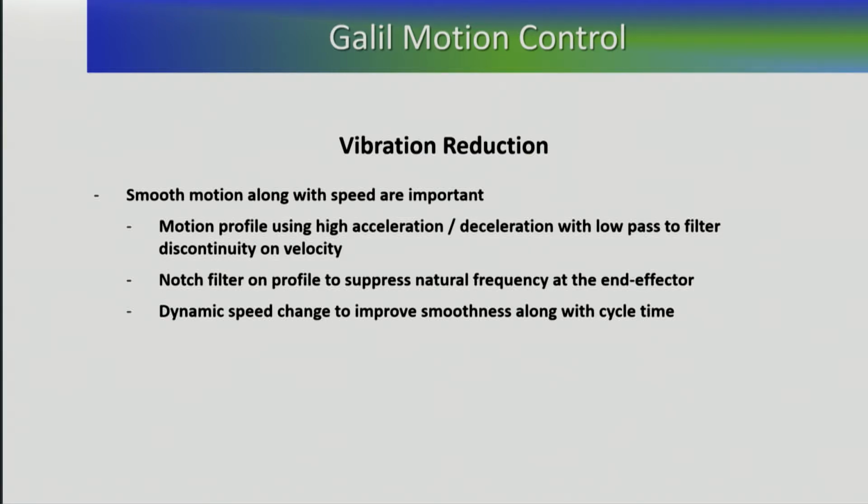When you're trying to address that, you basically have to say, I'm going to take the profile, and taking the profile, put it through the filter so that I can apply either a low pass and eliminate certain frequencies, or apply a notch on my profile. That allows me to eliminate a specific frequency or band of frequencies that do not go into the plant. And as a result, you no longer are going to be able to excite the resonance. So you do have an option to apply the filter not only on the output side, but also on the input side